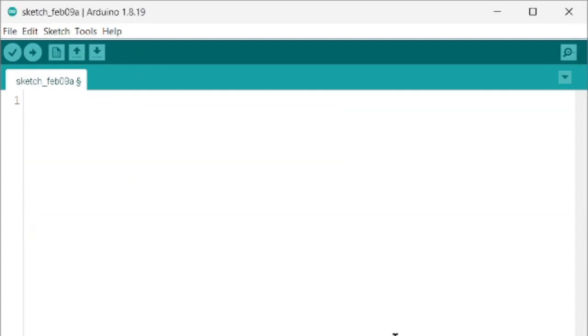The first line declares an array LED of type unsigned integer 8t that contains the pin number connected to the segments of the 7-segment display. The next two lines define two buttons, button 1 and button 2, that are connected to pin 2 and 3 of the board respectively.